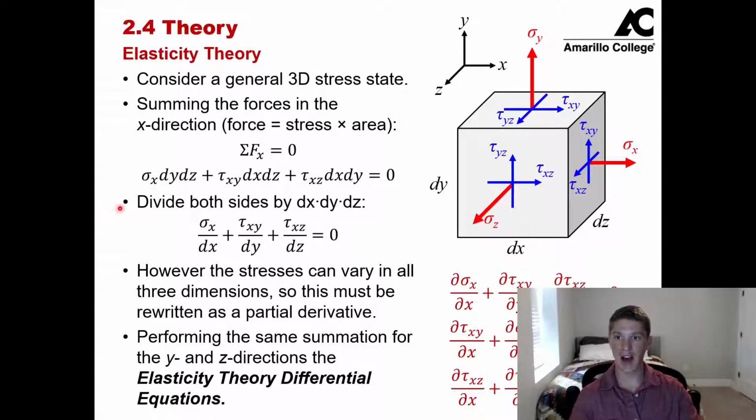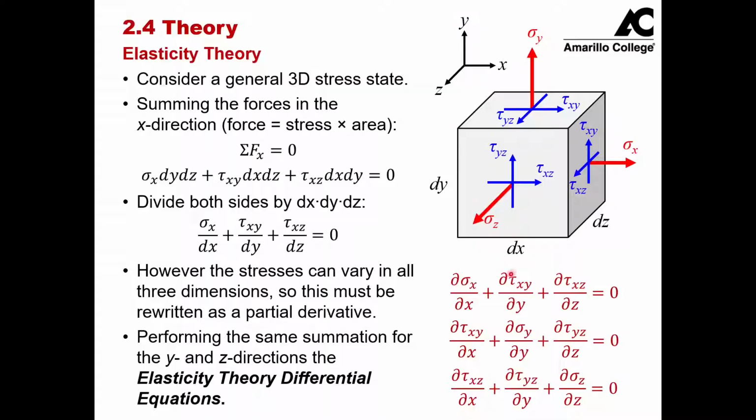And then we can divide everything by the volume of the differential element, so dx times dy times dz, and we get this equation right here. We can do the exact same thing in all 3 directions. If we do, we get these 3 equations right here, and these 3 equations are kind of the foundation of elasticity theory.